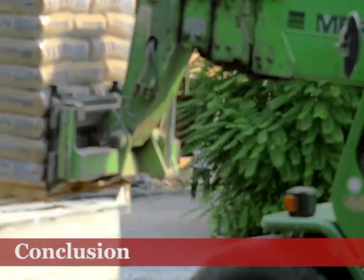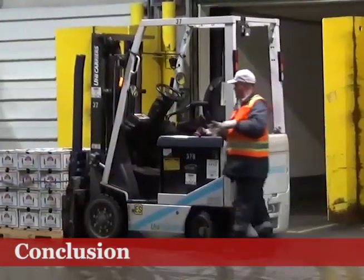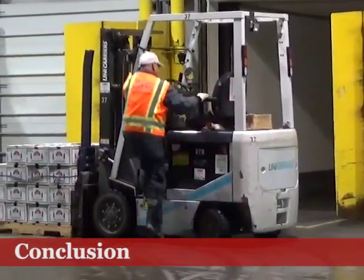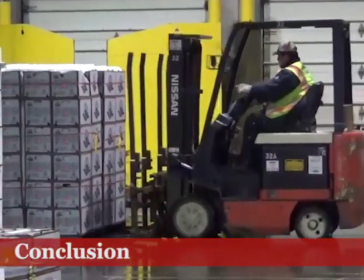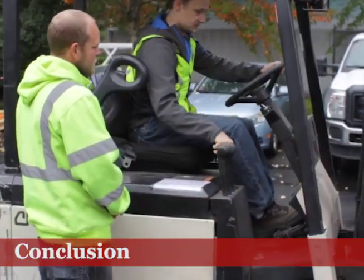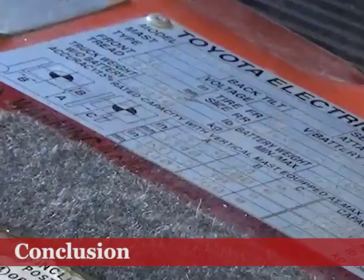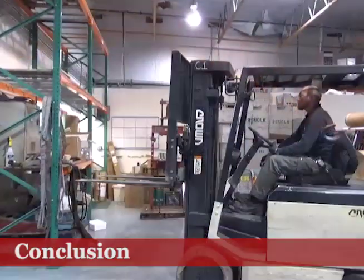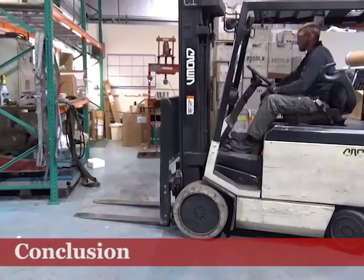The forklift is one of the most useful machines in the workplace, but it can also be dangerous. Treat it with the respect it deserves. You must know, and follow, the rules for operating forklifts safely. Only trained, and authorized, employees may drive forklifts. You must be familiar with the capacity, operating characteristics, and limitations of every forklift you operate.